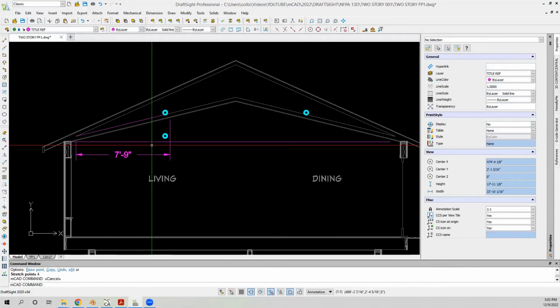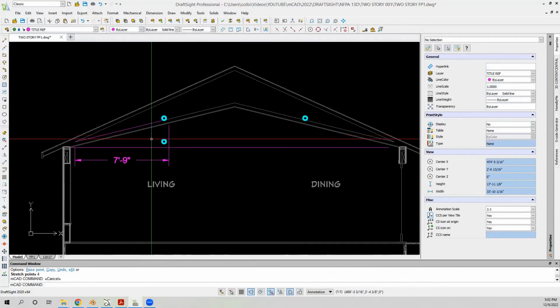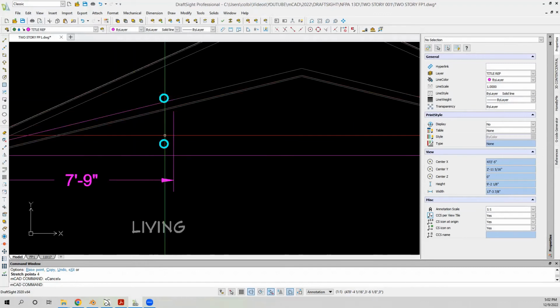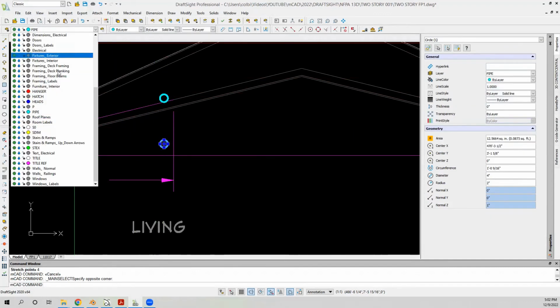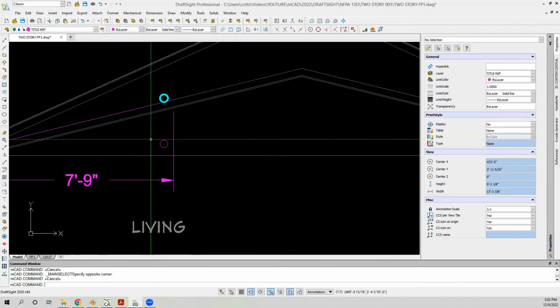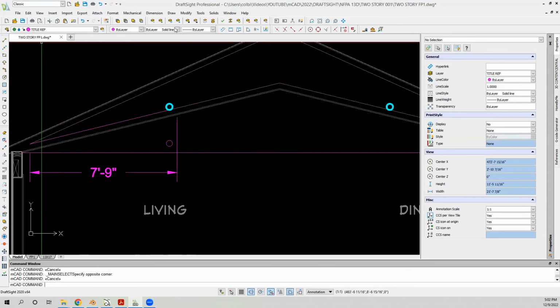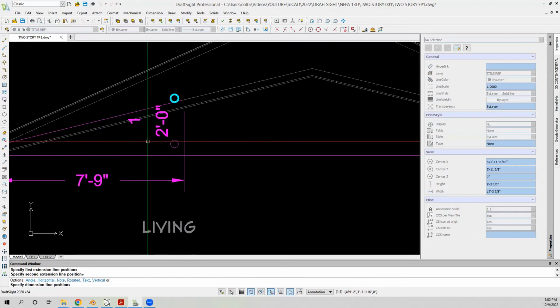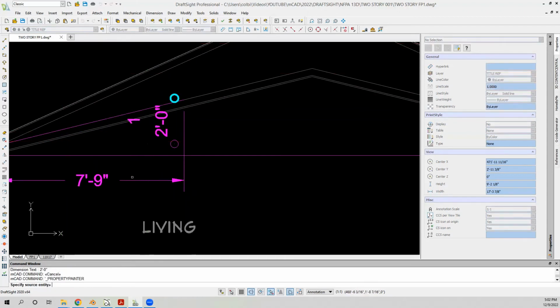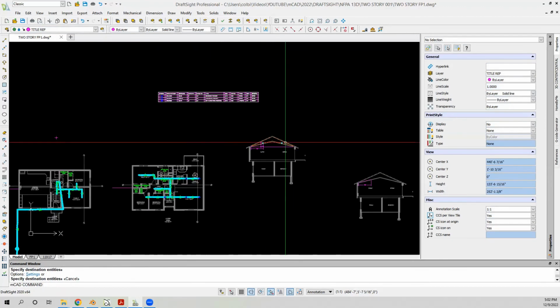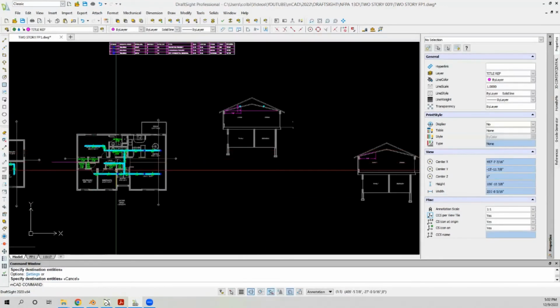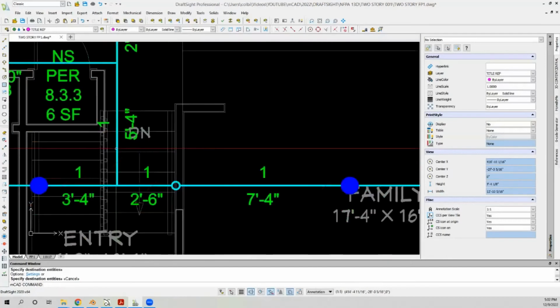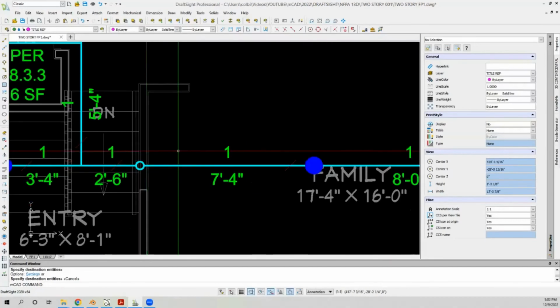So that's where the piping below would be at that elevation. I'm going to leave this here, but put it on my title ref layer so it doesn't print. And I'm going to put a dimension between these two, and change it to this dimension style. Okay, it's 2 feet. So my riser nipple right here is 2 feet.